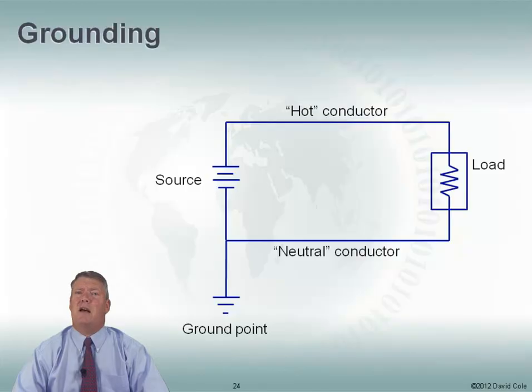So let's say we have a little metal case around our load, and here's our little guy, who comes and touches that metal case. This is the extent, by the way, of my artistic talent. You're seeing it right there. Our guy is grounded by virtue of touching the ground, so he's okay. He can touch this ground. There's no problem with that. He's not experiencing any kind of shock there.